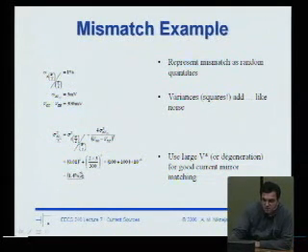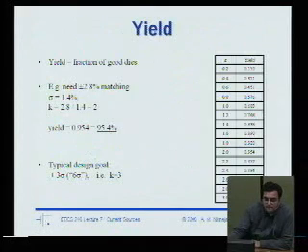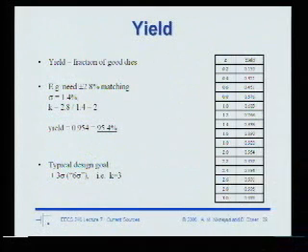Now, what does that mean? Well, this directly impacts the yield that your circuit is going to get. Let's say that you're designing an A to D converter, and if the mismatch gets too large, your A to D basically doesn't meet specs. We'll talk about what that means a lot more in 247. But from the perspective of this class, you need to design mirrors that are pretty precise.